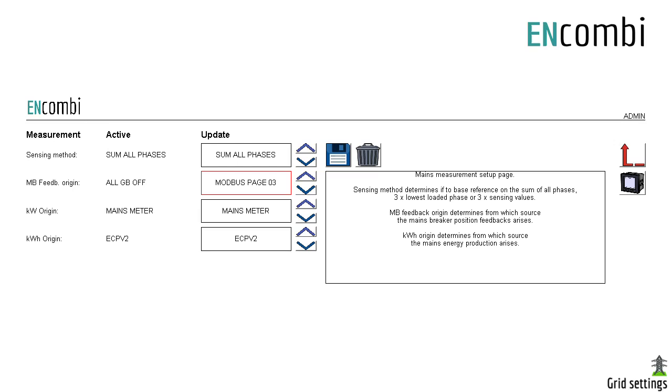This setting will be used for situations where the ECPV2 has to use the grid power data for interpreting the breaker position, which is written from a superior controller to the ECPV2 proprietary Modbus map page.